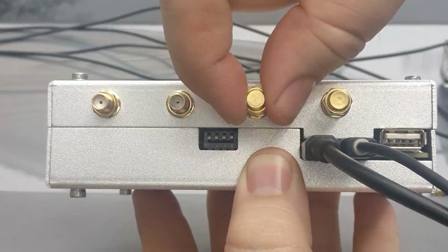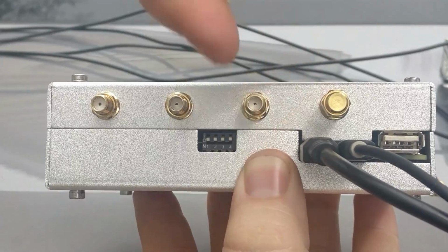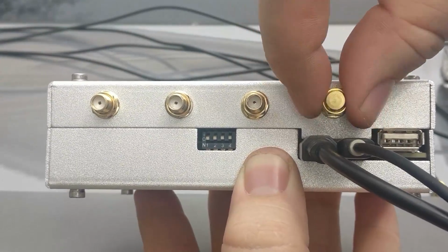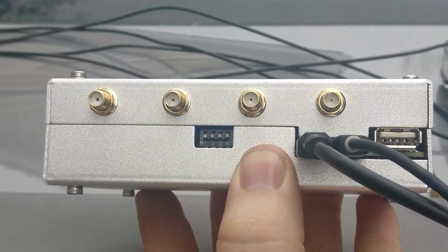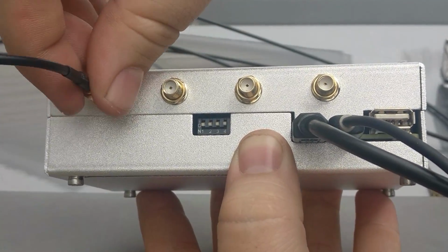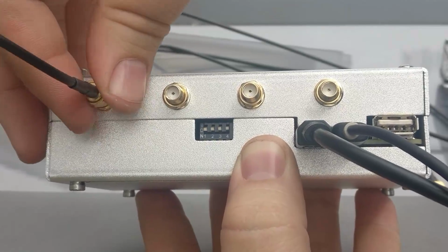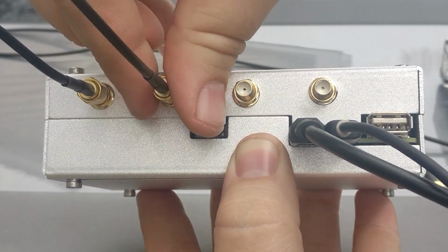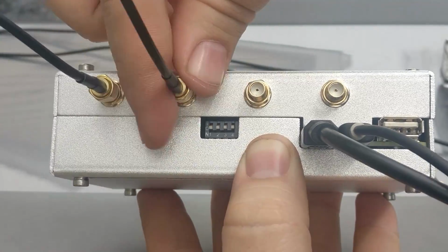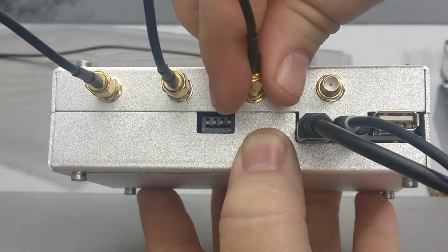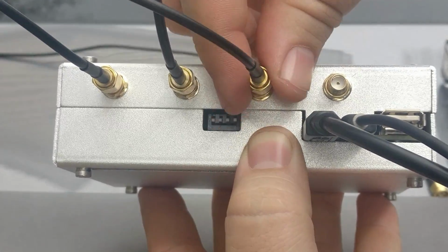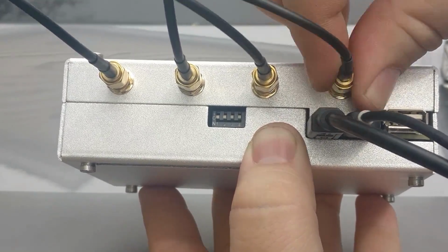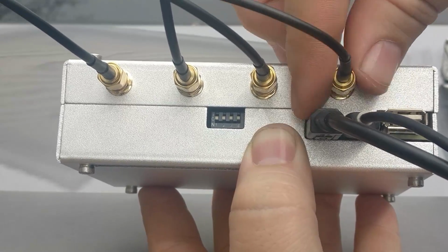Here you can see I'm taking off the terminations that you need to make sure are attached whenever you're doing your sync setup for your IQ calibration. Once you have those detached, you can go ahead and attach individually each one of your antennas, making sure that you have antennas 1, 2, 3, and 4 marked in some way, shape, or form, because if you mix up the antennas in your direction finding array, you're not going to get anywhere near a reliable result because your KerberosSDR isn't going to properly understand which direction your signal is coming from. So make sure you have those in the correct ports.